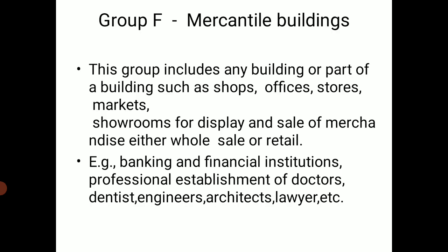Group F, mercantile building, means any building or part of a building which is used for the display and sale of merchandise, whether wholesale or retail. It can be shops, markets, stores, banking and financial institutions, and professional establishments of doctors, engineers, dentists, architects, etc. Examples include shops, markets, and financial and banking institutions.